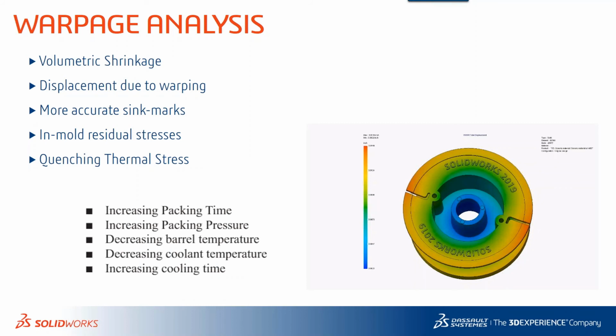So when we're approaching a plastics analysis, we always want to think of it as an iterative process. So we always start with that fill analysis. Then maybe our revision number 2 is a fill and pack analysis. And we're starting to get an idea, right? We're starting to recreate that injection molding process of injection, packing, cooling, and ejection, right?